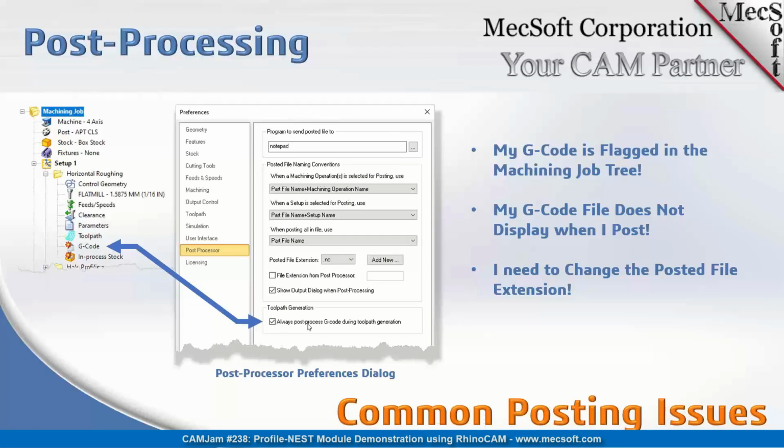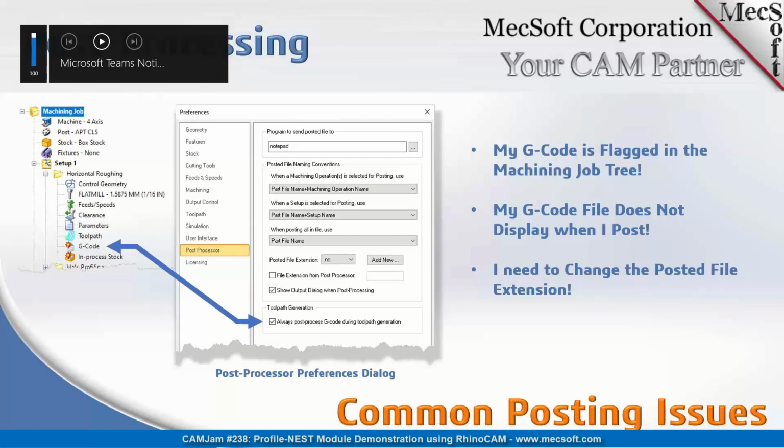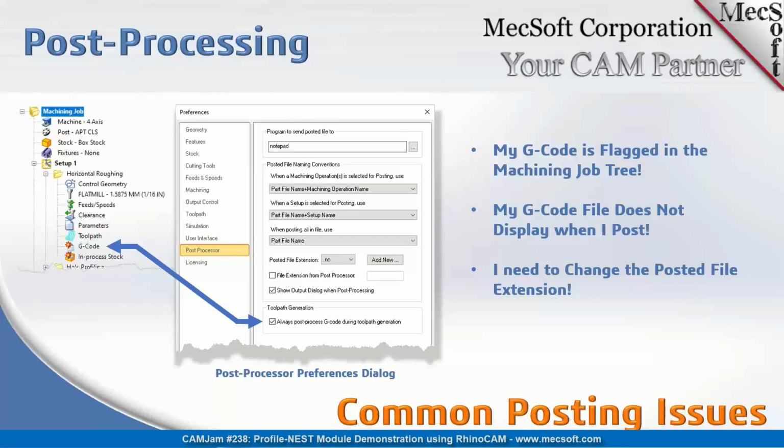And also, here's another checkbox down here called Show Output Dialog when post-processing. If you have this unchecked, it'll just go by default to one of these locations that you have defined here, and it'll pop up the G code file itself. If you have this option checked, it'll pop up a post and save as dialog, similar to saving any type of file. It'll display a dialog, allow you to select a location to put the posted G code file at.